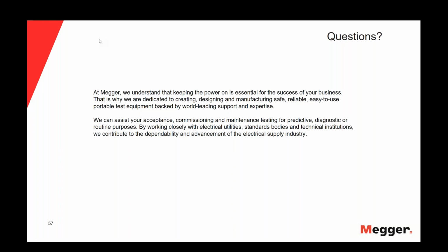All right, thank you, Robert. Henning, how long is the damped AC ramp charging time as compared to PF, CR, and sine? Okay, that's an interesting question, which was talked about a lot during the development of the IEEE 400.4. Obviously, let me start with the power frequency. Its power frequency is whatever power frequency, 60 hertz. What is it? 8 milliseconds. That's what you have available